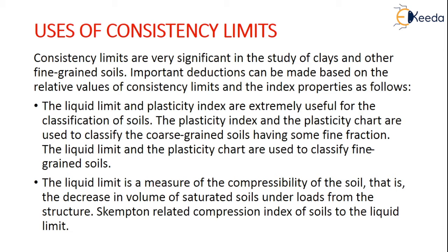Again, the plasticity index and the plasticity chart are also used to classify the coarse grained soils which have a high percentage of fine fraction. The liquid limit and the plasticity chart are also used to classify the fine grained soils.